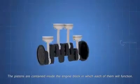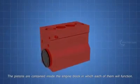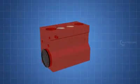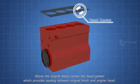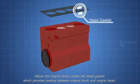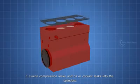Now, let's see how these parts work together. The pistons are contained inside the engine block, in which each of them will function. Above the engine block comes the head gasket, which provides sealing between engine block and engine head. It avoids compression leaks, and oil or coolant leaks into the cylinders.